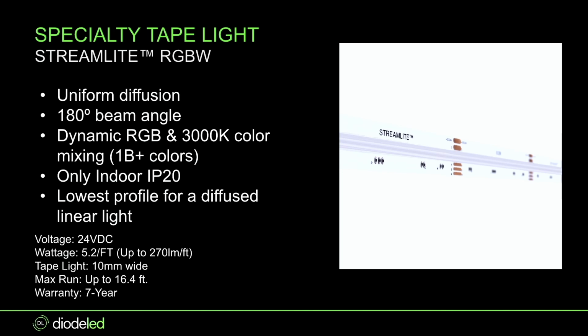You get, like most typical RGBW, all the RGB colors, and then with a 3000 Kelvin color chip on it as well. So you can mix and go between any color. You can add in white and then take the white out. And if they wanted to just switch from colors, they could switch back to just the 3000 Kelvin chip. And you can technically achieve different CCTs with it if you mix in the blues and yellows. There are ways to do that to make it a little bit warmer or a little bit whiter, but it's not technically as accurate as just an RGBWW. But I have some news on that here in just a little bit.